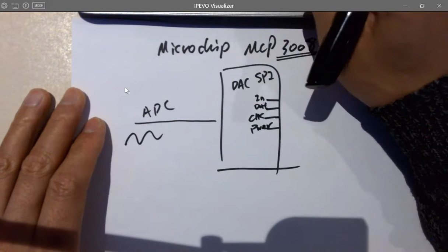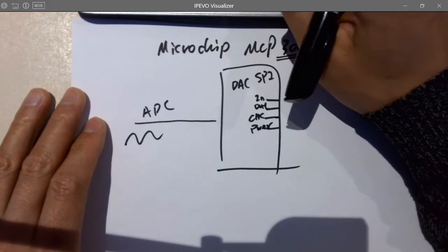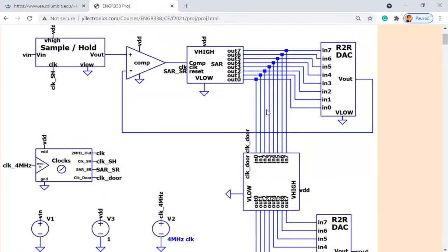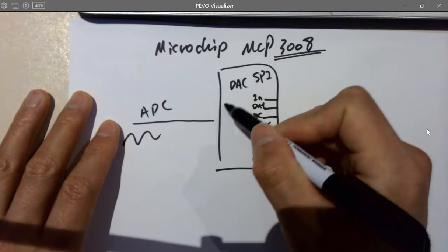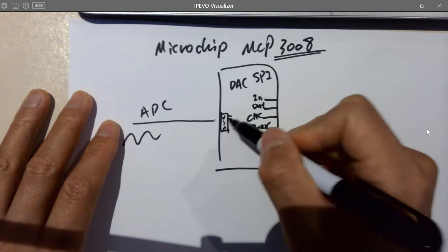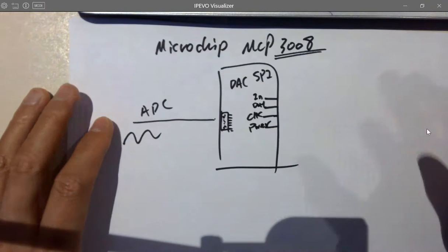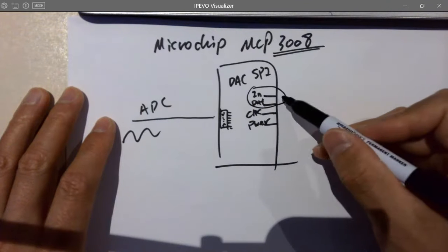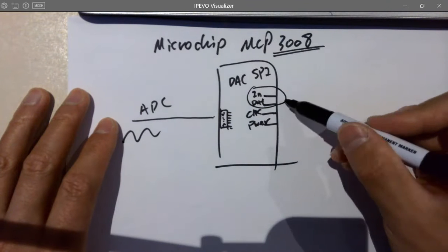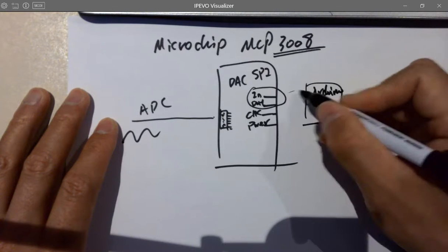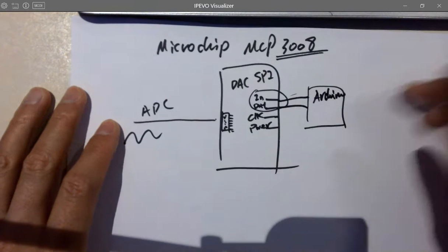So there will be a circuit very similar to ours. Internally, it's going to convert the analog signal into a parallel output, right? You're not seeing that, but internally, for example, there's a block that really does that, ADC. So you're getting a parallel output over here in a digital form, right? However, you got an in and out here, just 2 pins for communication with a microcontroller like Arduino or so. And you got another SPI interface over here to do that communication.